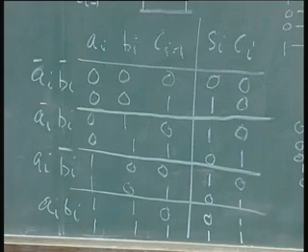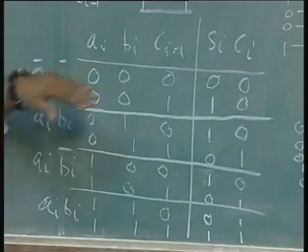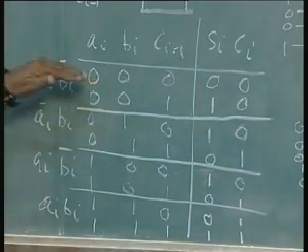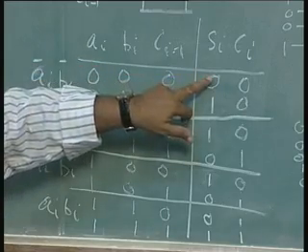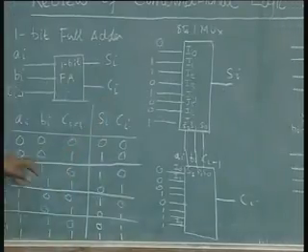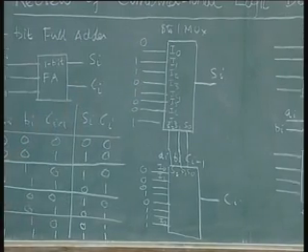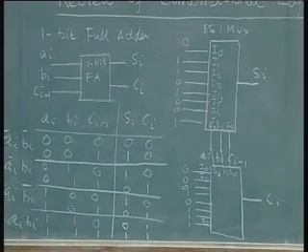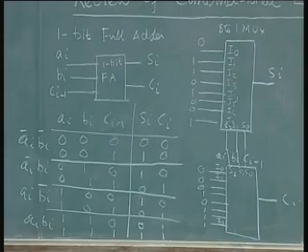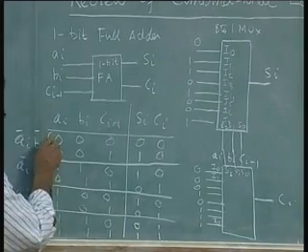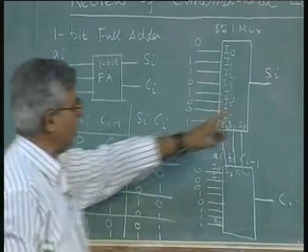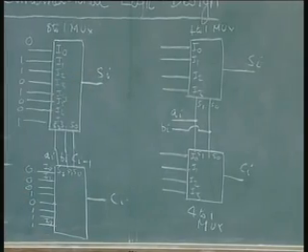Now, with this, how am I going to do this? Earlier I had one row corresponding to each input. So, I looked at the first row, found the input as 0, connected 0. Second row, found the input to be 1, I connected 1 to that. That is easy mapping. Now, you have to do a little more exercise here. Now, these 2 rows together correspond to the first input here, where Ai, Bi are both 0.